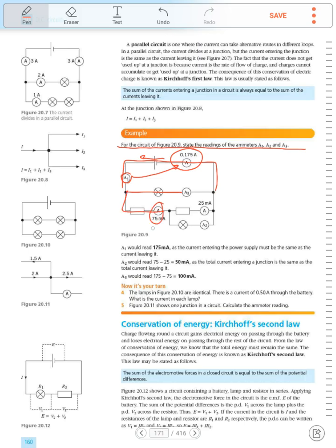This is 75 milliampere, so you can subtract this from the main current to find the current here. Now here the current is 25 milliampere, subtract it from 75 milliampere, so the current of this ammeter is 50 milliampere. The currents from this branch and this are summed together, and when they reach here, the current is the total of all of these currents.